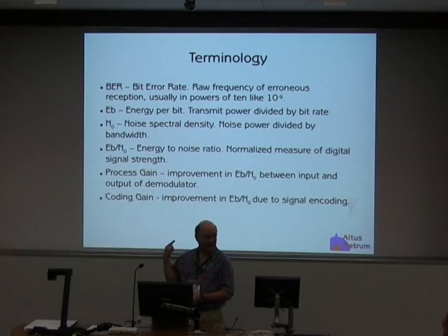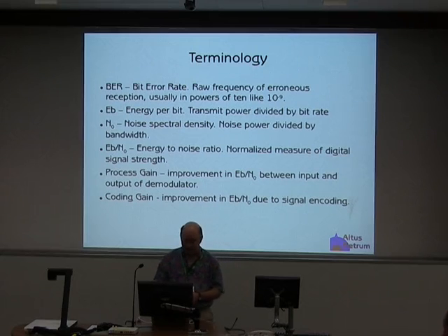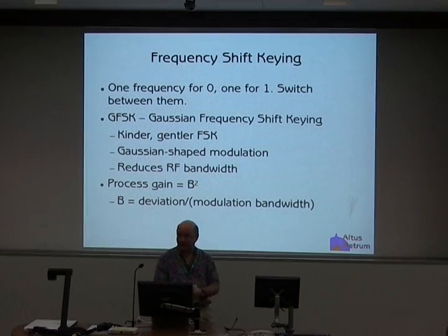So here we have two basically free pieces of RF improvements that you don't need to do anything like put more power into the air or build a larger antenna array, which annoys your neighbors. All you have to do is be smarter about your beyond the receiver bits and beyond before the transmitter bits. And that's what I want to talk about: coding gain and process gain.